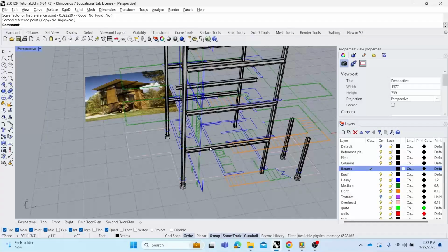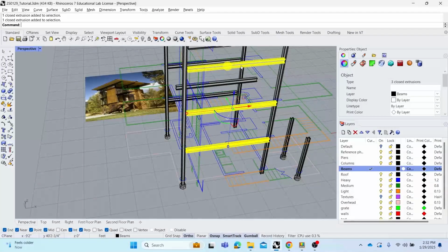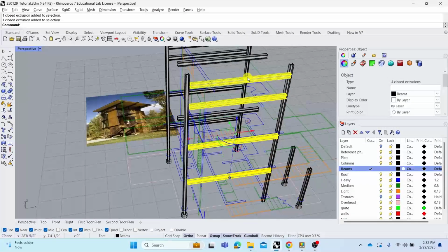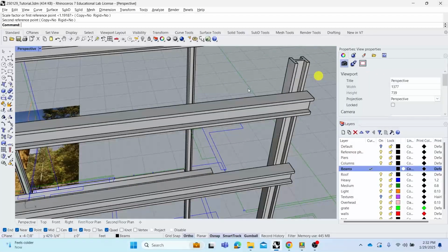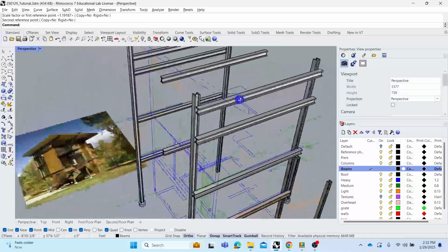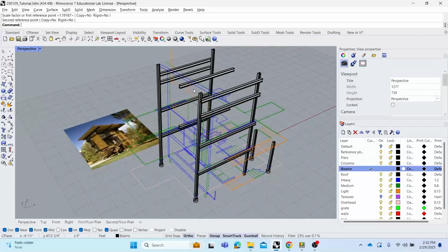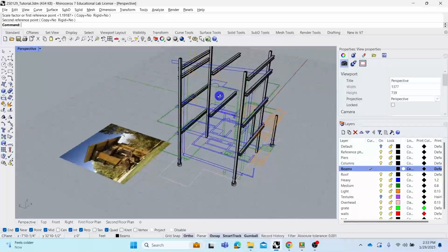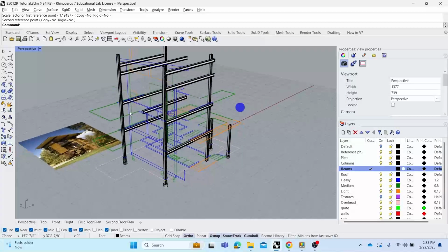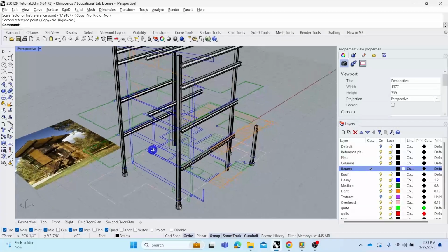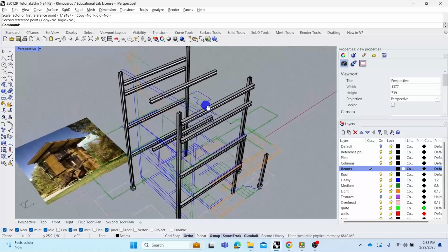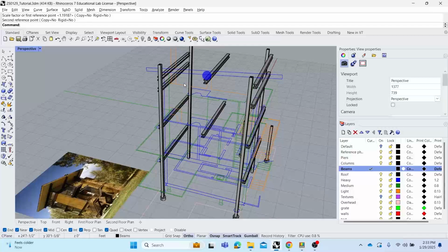It just means that instead of extruding them to the face, I actually need to extrude them to be proud. So I'm just going to go to my midpoint and go to this edge and go to the edge of the column like that. There we go. We can do the same for the other side, but I'll let you do that. Next up, I'm sure we have beams running this opposite direction. What I'm just going to do quickly is